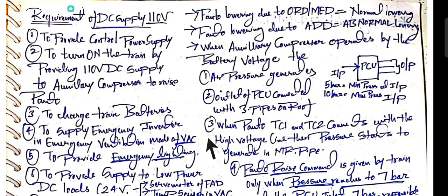And the last, the fourth supply which we have, is single phase 240 volt AC supply. And as we all know, what is the requirement of this supply? This supply is for providing energy to sockets in order to charge the phone or the laptop, also known as socket supply. Okay, so these are the basic four types of auxiliary supply.